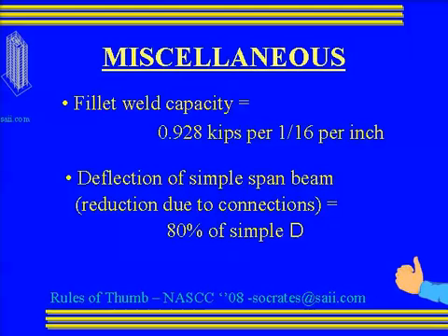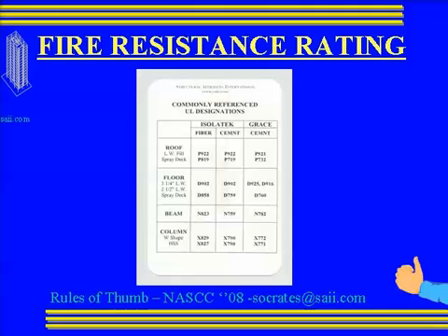So these are some of the usual UL numbers that we use typically in hospital and office construction. For composite floors, it's either 902 or 925, 916, whether you're using Isolatek or Grace.